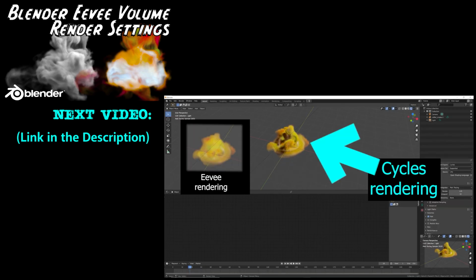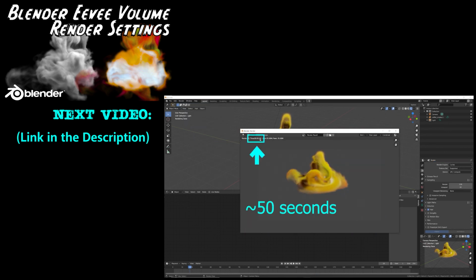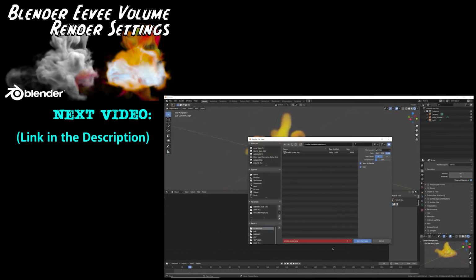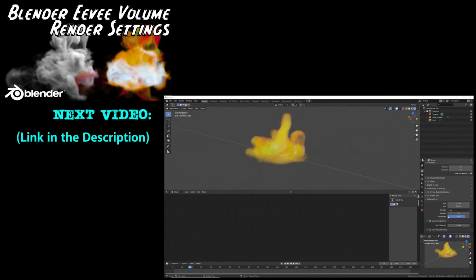There's another part to this video that demonstrates how to set up Eevee's render settings to increase the render quality. I do a render comparison between Eevee versus Cycles. I pump up the quality of the Eevee render by configuring the render settings and try to get a quality closer to that of Cycles render. Why would I do that? Because Eevee renders a lot faster than Cycles, but Cycles gets you a really great result even with just the default settings. By configuring Eevee's render settings, we can get quality and speed.